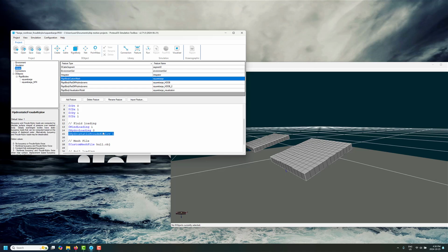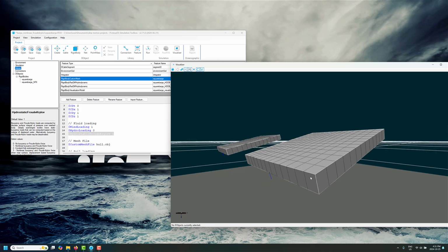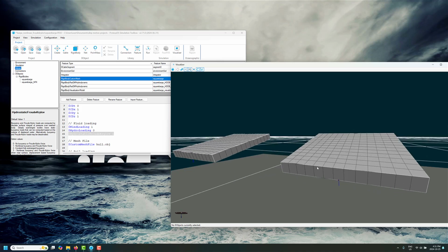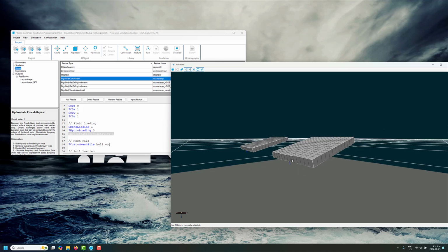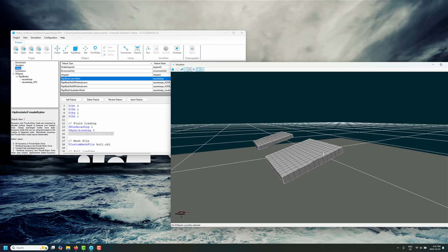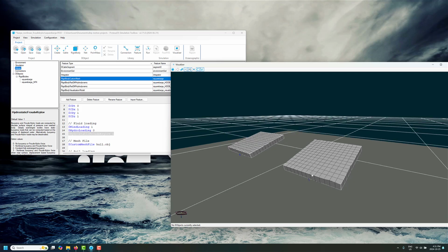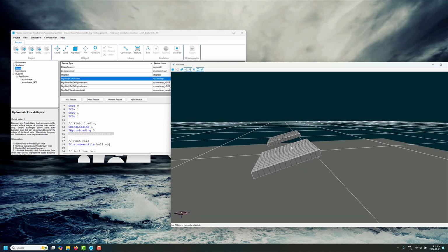And this is the key one here, the hydrostatic Froude-Krylov loading. So what Proteus will do is at each instant in time, for any wetted panels that are below the water surface, it's going to be calculating the static and dynamic pressures on each of those faces and applying the forces to the rigid body overall through time. And a good reason to do this might be in extreme conditions when there's lots of changes in the wetted area of the hull through extreme waves or something really severe is happening. You might get a little bit of a better capture of the dynamic effects from that.